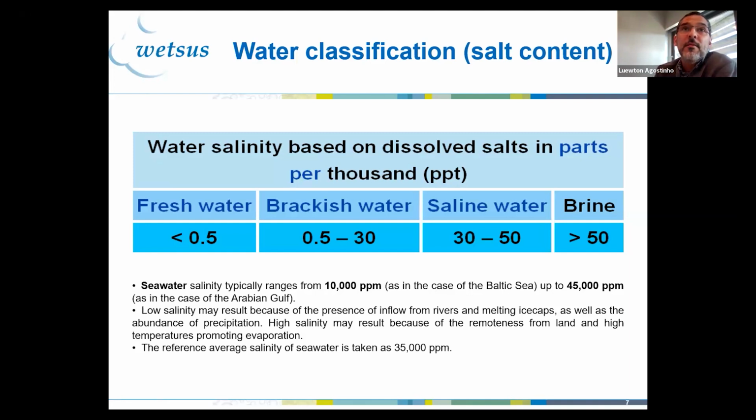In the industry, but also in the desalination plants, right? Because when you desalinate seawater, let's say you get 35 more or less. And then you normally do freshwater 50-50. So on one side, you have water below 0.5 that you can distribute to the population. And on the other hand, you have a concentrate, a brine, that can go up to close to 70. That's what we call the brine. And normally what we do with this brine, do you know? Yeah, you bring it back to the sea.